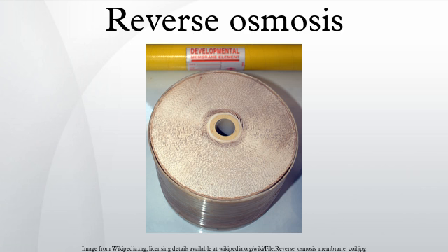Reverse osmosis is extensively used in the dairy industry for the production of whey protein powders and for the concentration of milk to reduce shipping costs. In whey applications, the whey is concentrated with reverse osmosis from 6% total solids to 10–20% total solids before ultrafiltration processing. The ultrafiltration retentate can then be used to make various whey powders, including whey protein isolate. Additionally, the ultrafiltration permeate, which contains lactose, is concentrated by reverse osmosis from 5% total solids to 18–22% total solids to reduce crystallization and drying costs of the lactose powder.